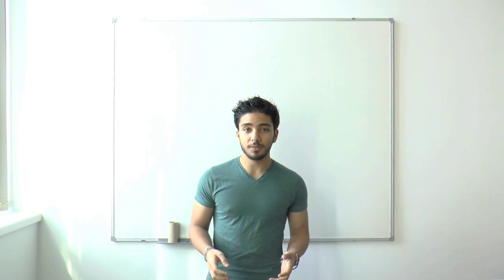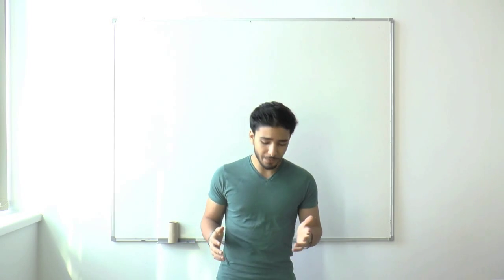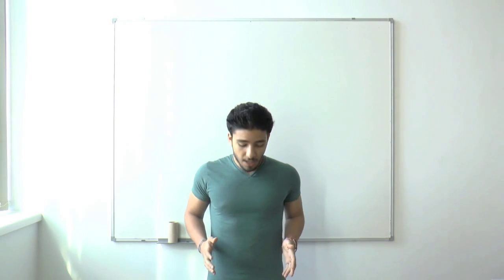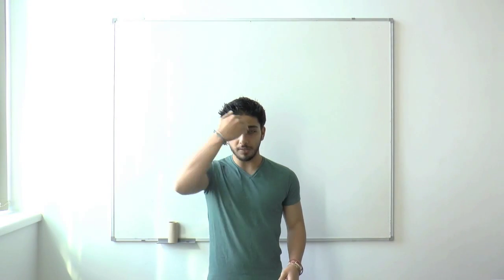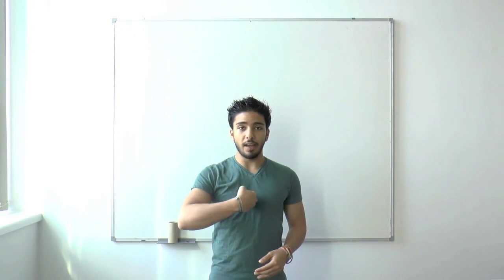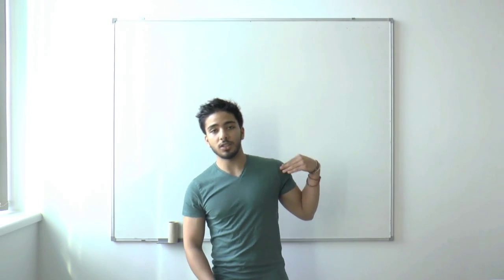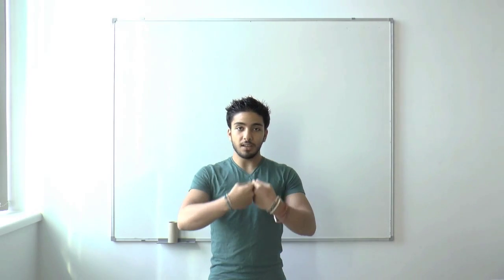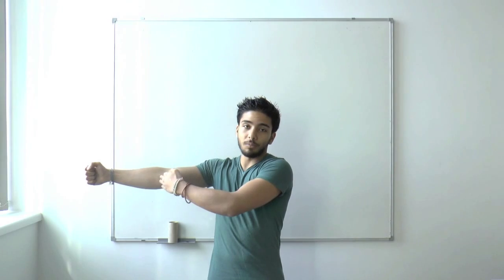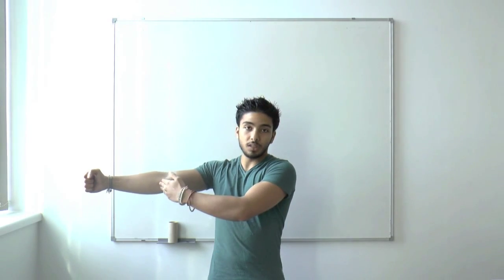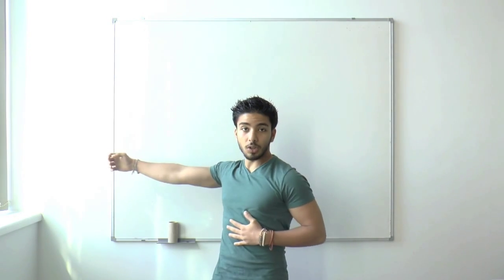So the last part of the mast we have to analyze is torsion. Now, what is torsion? Imagine I am the mast and a force acts along this axis, along myself. If a force acts on this axis, then it's going to cause the mast to bend, whichever direction it acts in. But if we offset that force along another axis, for example, if it acts along my arm, then that force is going to make me want to twist. And this sort of motion is called torsion.